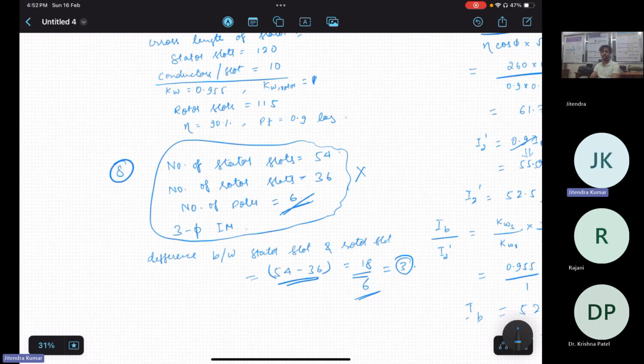So mostly you guys design concentrated winding or distributed winding? Concentric, mostly concentric. All the traction motors are concentric. Yeah, that's very convenient also. And this BLDC, you mean a square wave or trapezoidal current, right? Trapezoidal current or also sinusoidal current? Sinusoidal current. In the controller, the electronics department will take care of when to on, when to off, and we are taking care about the windings and how much slot pole and what is the air gap. These basic things.